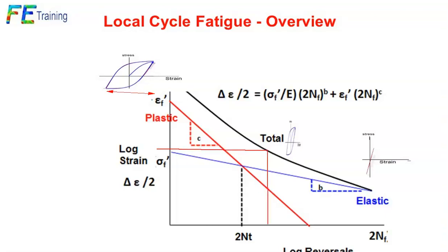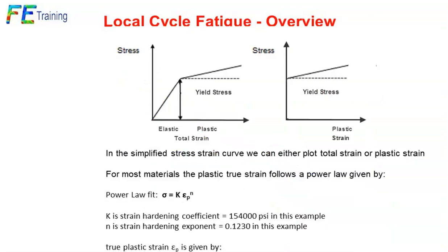And that's going to be including the plastic effects. So if I've got plasticity, I've got very high levels of stress, then that's okay. So up in here, I could actually have a very short life, and that could be of the order of, say, 500 or 600 cycles, and that's okay because there's a large amount of plasticity associated with that. I've taken care of that. So it's not a number transition, it's actually a material behavior transition. It's the presence of plasticity.